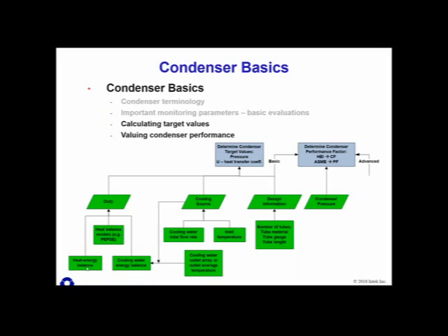And so you look at the heat input to the steam cycle and the electricity outputs, the energy outputs. You subtract the two, and you get the condenser duty. That's called the heat input method. If somebody wants me to go into that in more detail, I can. I don't actually have a slide on that, but it's very straightforward. But that's a decent way to get condenser duty if you don't have reliable methods for either of these other methods here.